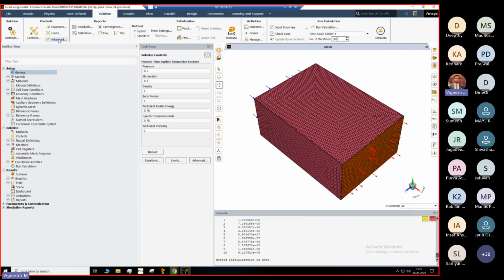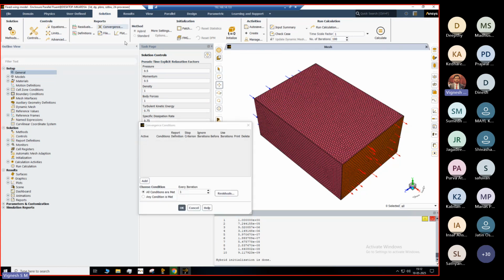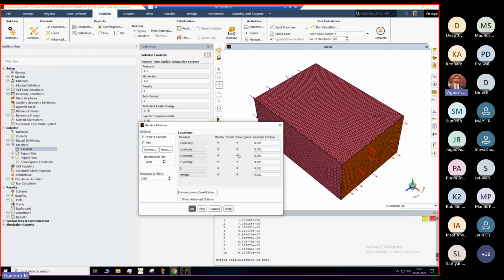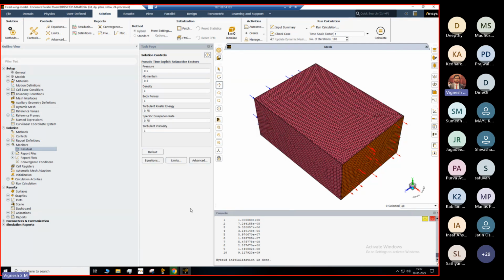One more thing you can look at is the convergence. You can activate it from here, the residuals. I'm just keeping this default. If you want, you can also change this to e to the power of -6, where your accuracy may improve. But since it's a demonstration, I'm not going to play much on that. So I just keep that default, but also make sure you have the right residuals for your problem. So I'm just making it 100.